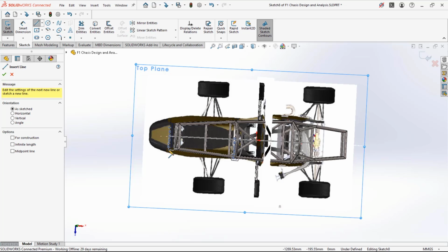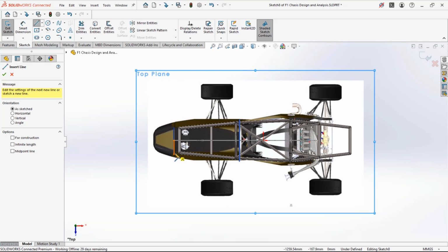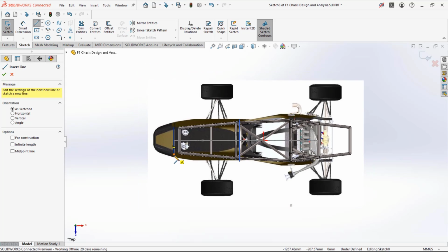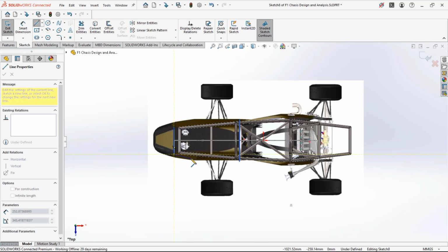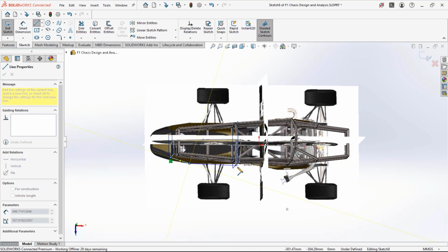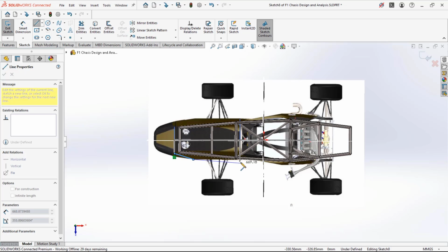You need to refer the sketch because you are using the loft. The guide curve should lie on the profiles as well, or else it will create errors in the design.